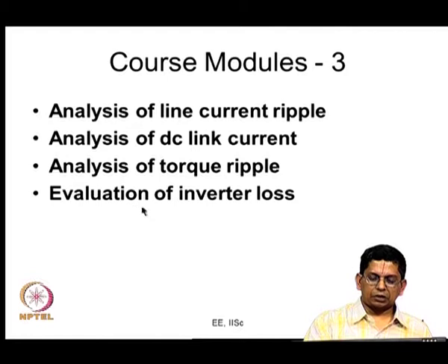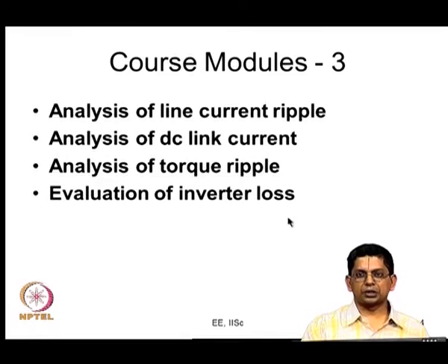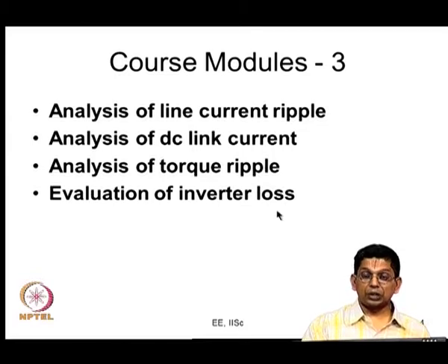So, in this module we had 3 lectures, the first one focusing on conduction loss, the second focusing on switching loss, and the third one exclusively focused on this reduction. We looked at these advanced bus clamping PWM methods, and we saw at least some directions in that regard, how they could be used to reduce the inverter switching loss and also the power conversion loss.